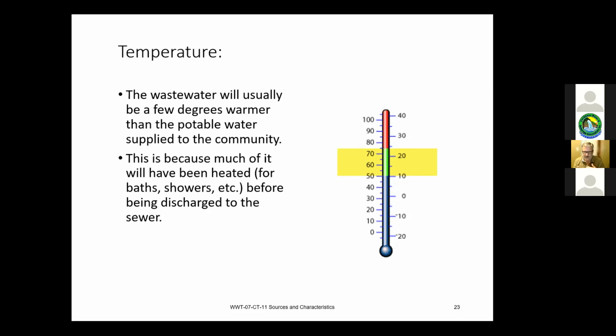The way you're going to combat those lower temperatures, I'm assuming you all live in very nice warm areas, so you may not have to deal with this, but what we do is we have to increase our mixed liquor suspended solids, increase our bug mass in the wintertime. So we have a larger bug mass to do the same amount of work. And by larger, I mean anywhere from 1,000 to 1,500 milligrams per liter. We'll talk more about those solids contents later on in this series. But we're basically just a little bit shy of doubling our bug mass to perform the same treatment in winter as we do in the summer.